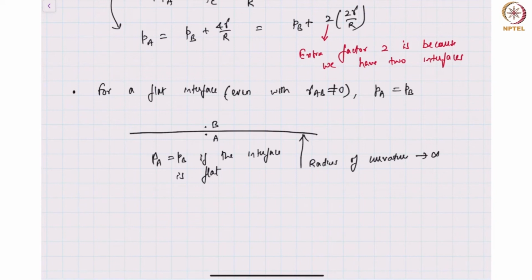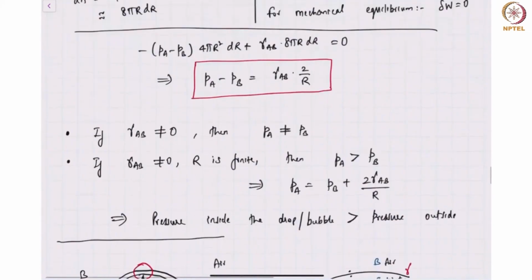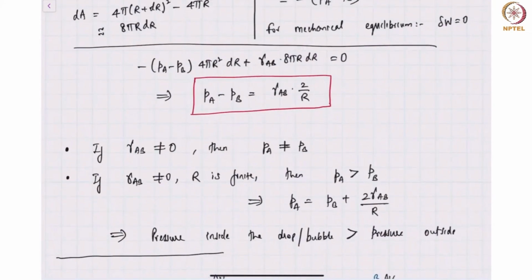So even though I show 2 points on either side of the fluid, we have to assume that these 2 points are very, very close to each other and just across the interface. So there is no appreciable change in the vertical height, if there's gravity. So there is hardly any variation in hydrostatic pressure because the effect of gravity in this particular statement is negligible. So the statement that is shown in the box here ignores gravity because you're looking at cases just across an interface.